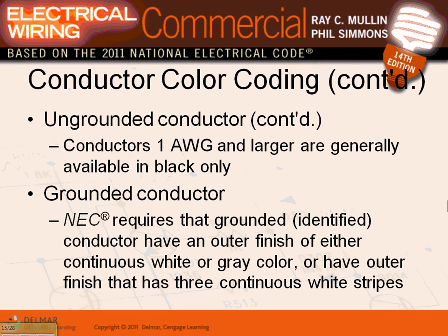So again, you can use one color code for all three phases. By the way, for the three phases, do I have to identify phase A, phase B, phase C by code? No. If it's one voltage system, you really don't. But most people, just because of good engineering practice, will make this one black, this one red, and put a blue color here on phase C, just to identify.